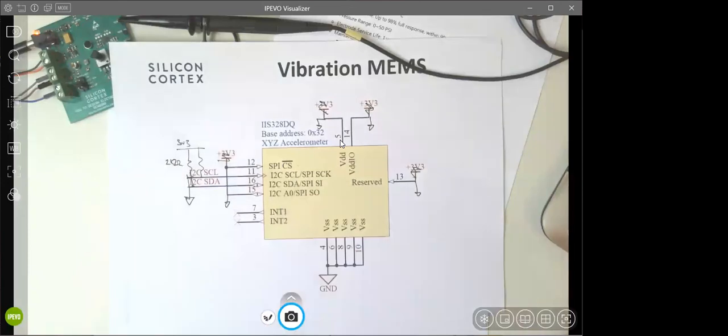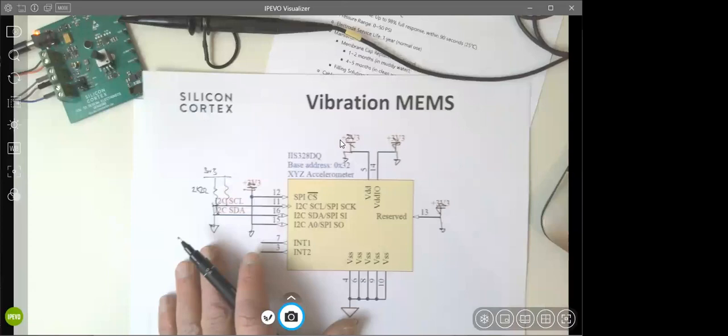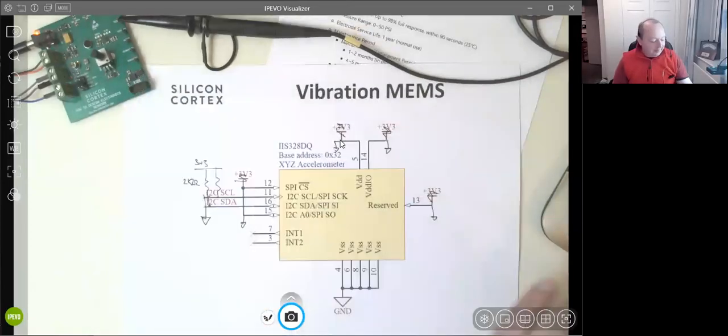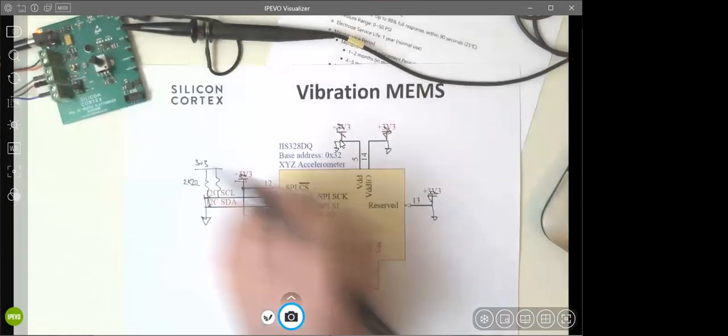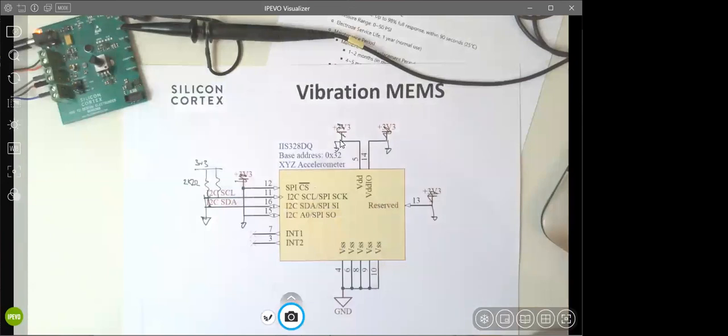I had that problem with a DVI cable into some kit, and the pull-ups on the source were enough to power the board when you turned the board off. Yeah. Or enough to break the reset circuitry, so when the power came on, it didn't reset. Yeah, it was a big problem.